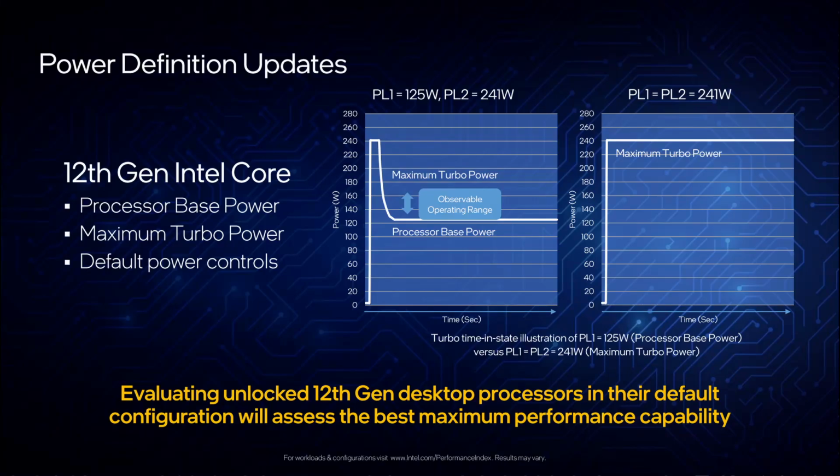Obviously, Turbo Boost 2.0 is available in Alder Lake as it's the main driver of performance above the base frequency. A major difference between Alder Lake and any previous Intel Core processor is that, at least for the K-SKU CPUs, PL1 is by default equal to PL2. This is very different from before, where PL1 would equal the TDP and PL2 would range from 200 to 250 watts. This effectively means that Intel has enabled near unlimited peak turbo by default.